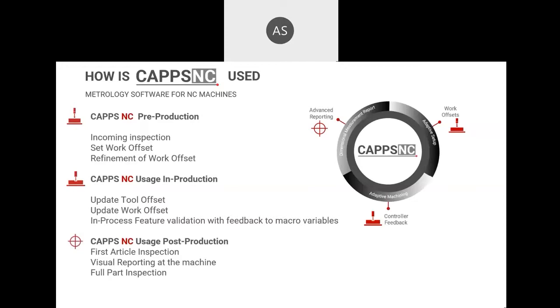And it's extremely important. The true position, let's say, is very tight of those holes in the hole pattern to the center hole. Well, you could machine the center hole and then probe the center hole, update the work offset based on the deviation of that center hole. And now when you drill the holes in the pattern, they're going to be a lot closer to the center hole than they would be if you didn't do that. Okay, so let's say you're maintaining, let's say, a true position tolerance of 5 thou or something like that, something that's really, really close.